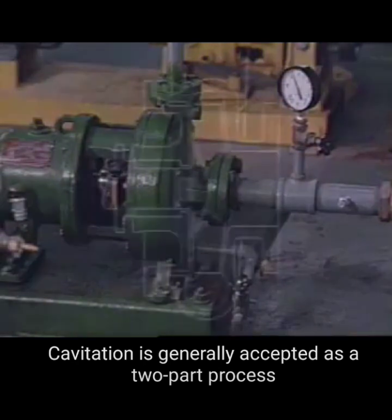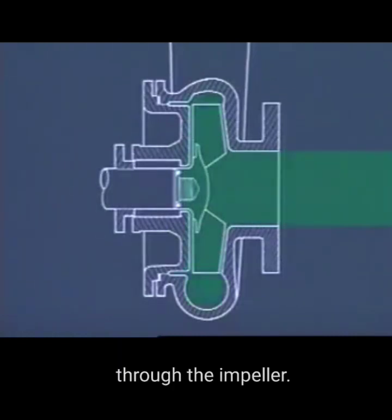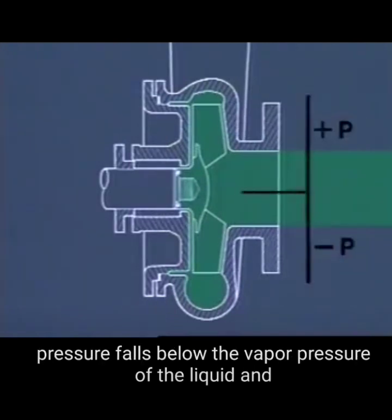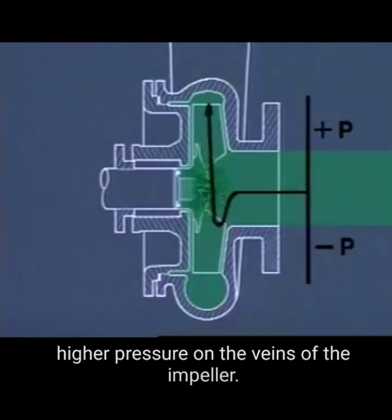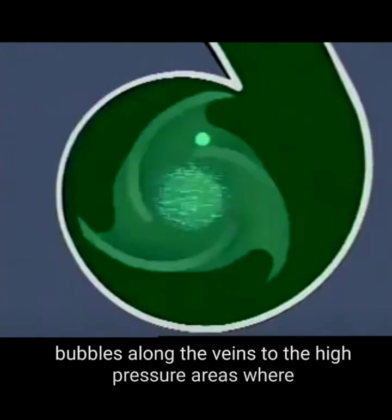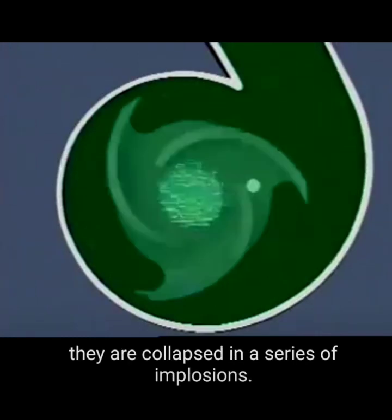Cavitation is generally accepted as a two-part process caused by the changes in pressure as the liquid moves through the impeller. The first part of the cavitation process occurs when the pressure falls below the vapor pressure of the liquid and vapor bubbles are created in the eye of the impeller. The second part of the process occurs in the areas of higher pressure on the vanes of the impeller. As the impeller rotates, the centrifugal action moves the bubbles along the vanes to the high-pressure areas, where they are collapsed in a series of implosions.